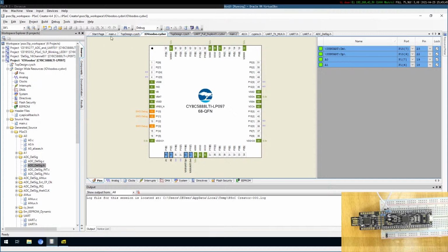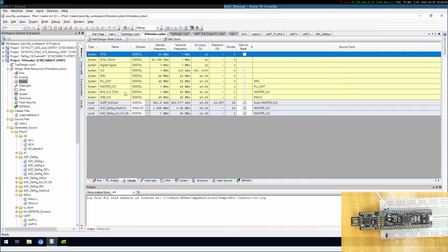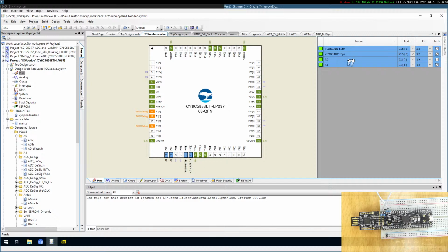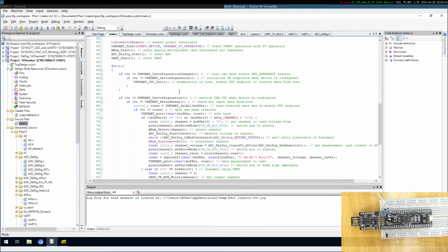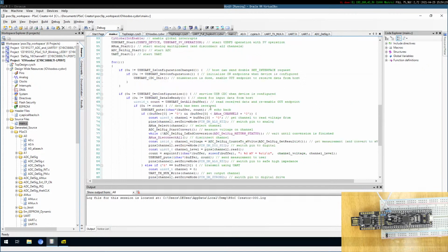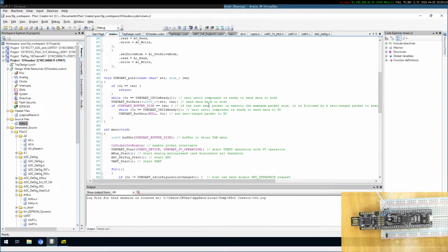So I had to use this IDE because you have to program the device using it. It is a bit different because you also program all the clocks yourself. You have to program which pin things go to. So here, for example, the A0 signal, I've mapped it on this pin, but you can map it on any other pin. It will do the routing for that. And then I wrote demo code to figure things out.